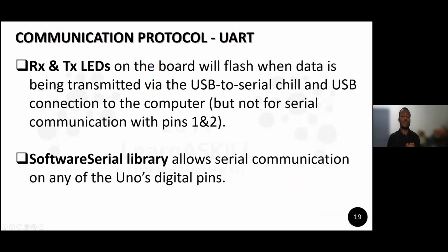For UART communication to proceed, both devices should be capable of UART, and like I said, you connect RX of one to the TX of the other and TX of the first to the RX of the other. The same thing happens when you are communicating between your computer and your Arduino. The USB ports in the computer have signals called D plus and D minus, and there is a shift over.